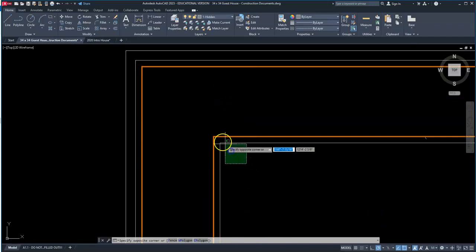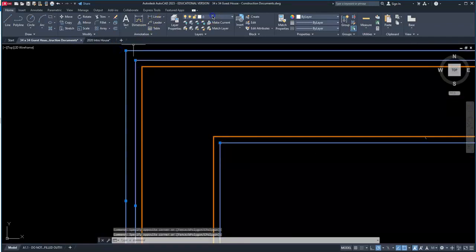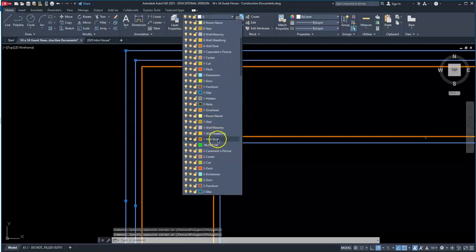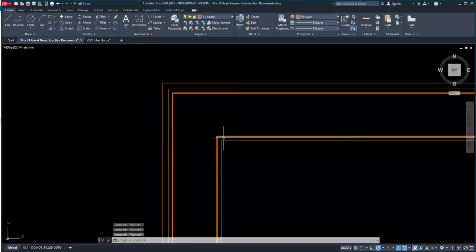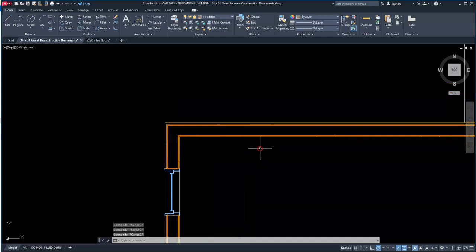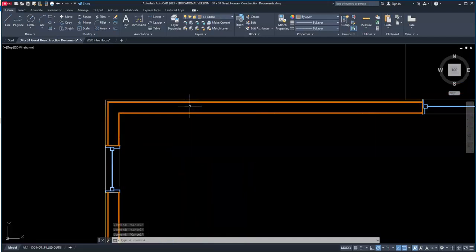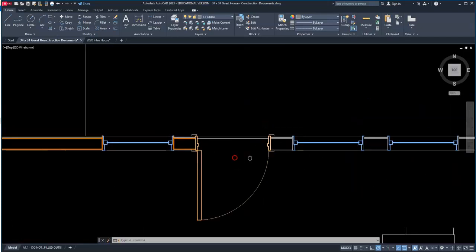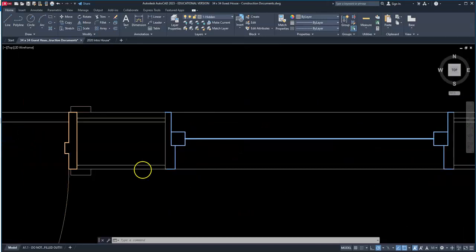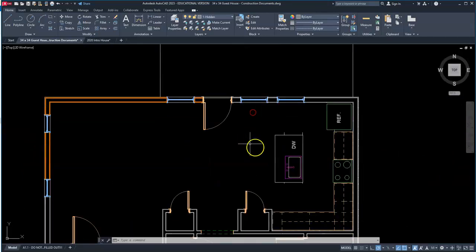Same deal. We'll go to the interior and exterior and change to wall sheathing. You can select as many lines as you want. Just be careful if you happen to press the escape key, or you might bump your keyboard or your mouse. You may lose everything you selected. So I always like to just select a few lines at a time, but that's completely up to you.